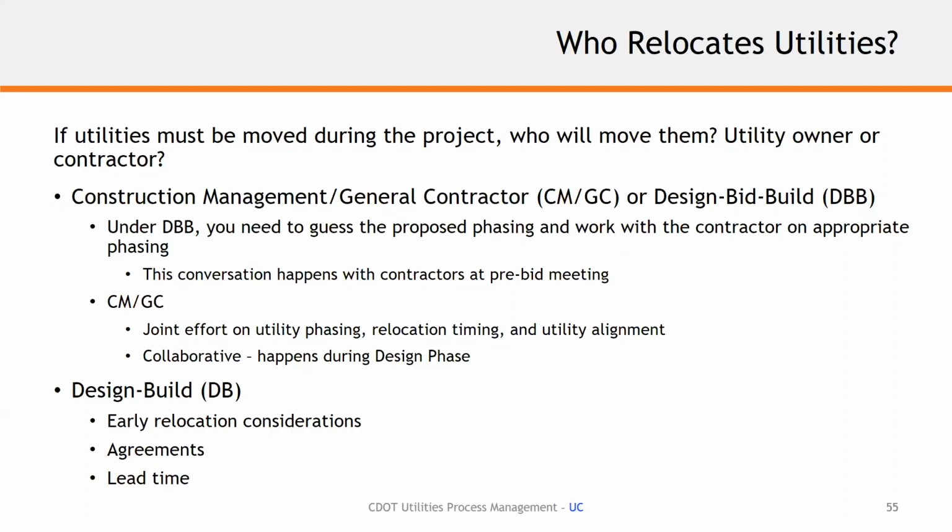And then when we look at design build, we're looking at a couple of things. We would like to see SUE, subsurface utility engineering, completed from 0 to 10% design, pre-RFP, included as information to the design build bidders and allowing them to move forward with a 30% design that they are bidding on in the RFP process, so that they can then move into final design.